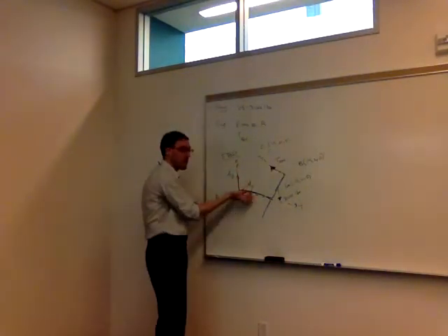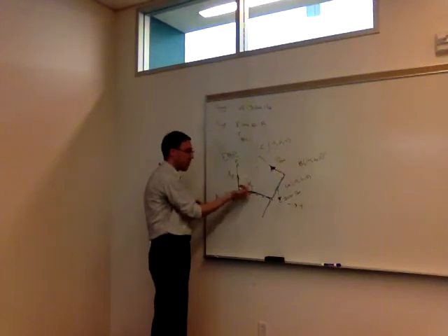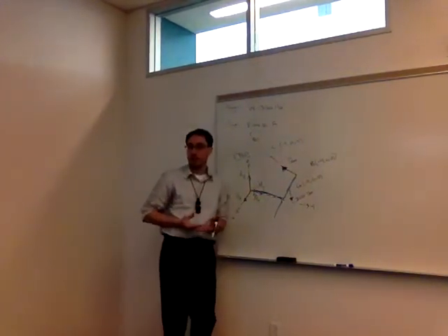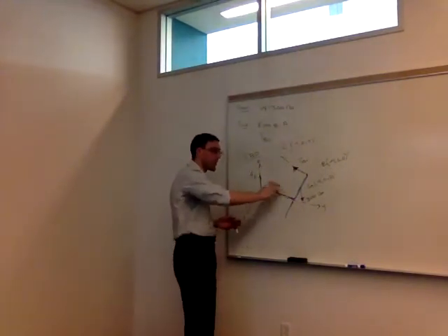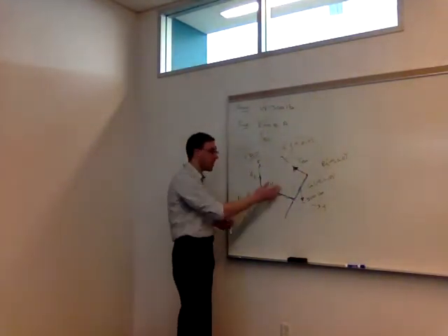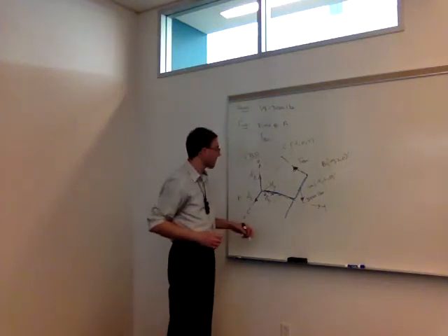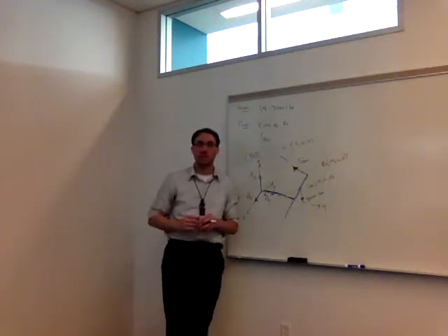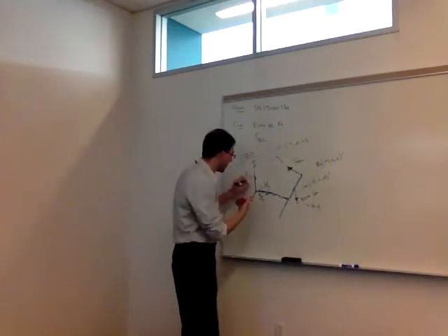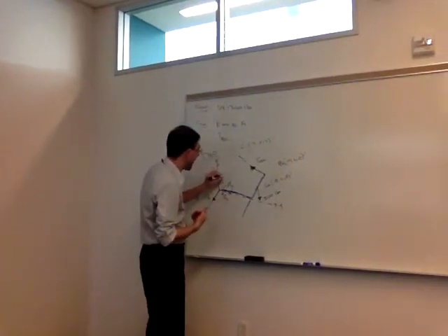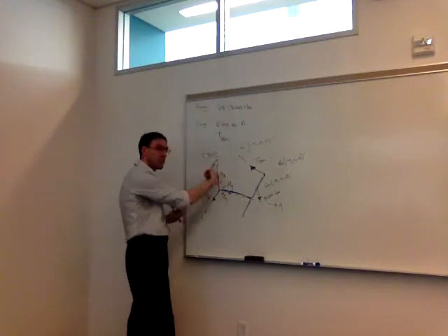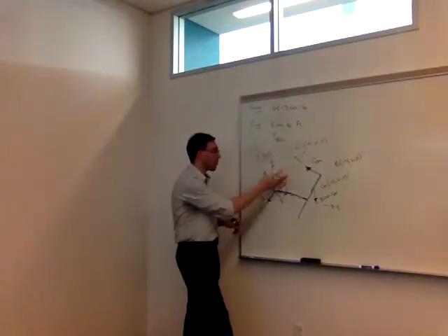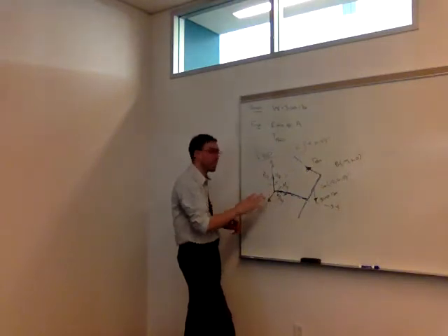Right, so if I put my thumb in the direction of y, the way my fingers curl is the positive direction it would be. Again, this is an assumption I'm making because it prevents twisting counterclockwise or clockwise, so I'll just assume it's positive. And then around the z direction, can we twist it around the z direction when it's pinned at A? Right, that's also prevented, so we'll have an Mz, I will call it. Again, assuming it's positive around the z direction. Right, so we went through all 6 possible degrees of freedom there.